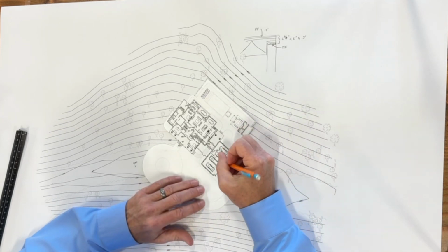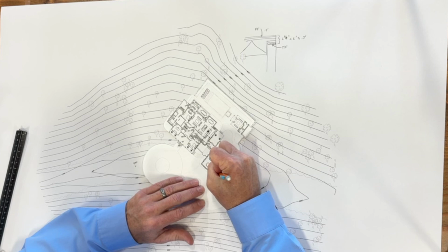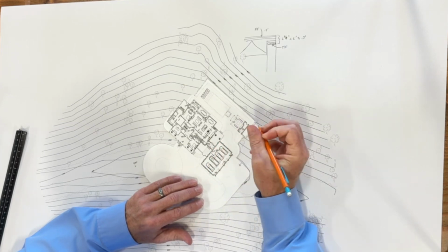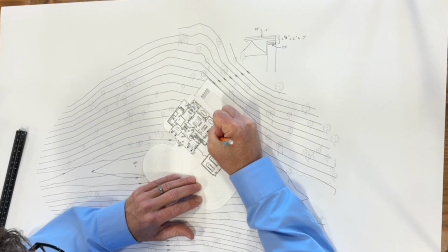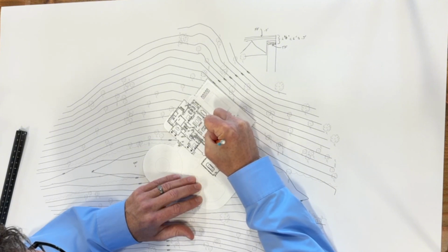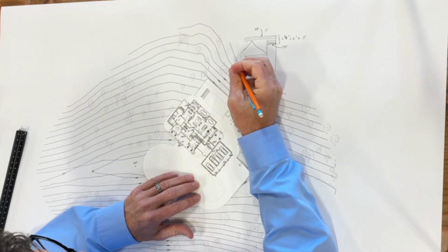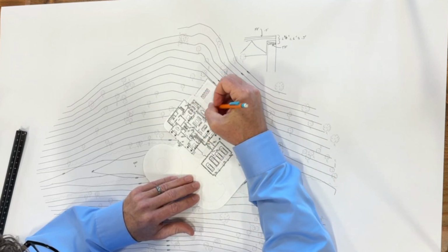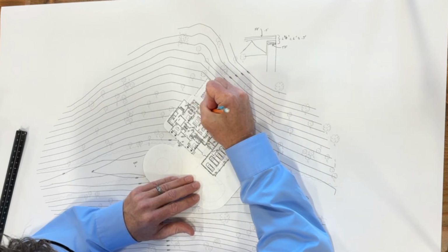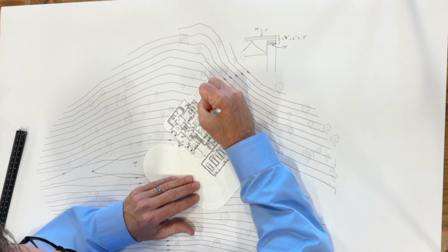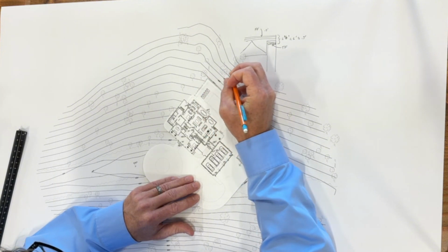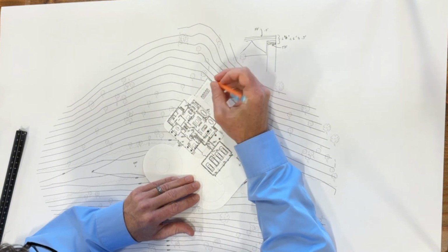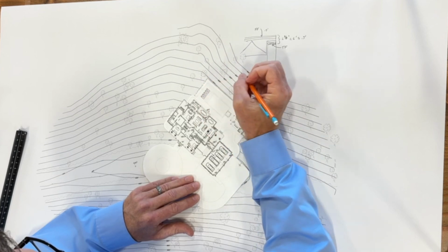So, okay, we now know, and by the way, this garage, because they're always flat, it's 941 all the way across the front. You've got a door here, that's a 942, and another door going outside, so we'll call this a 941.5. So we're establishing where the heights are everywhere. Okay, now, if it's a 941.5 right here, you're probably going to go down to a 941 out here. That means the pool, we've got to set what the pool elevation would be.